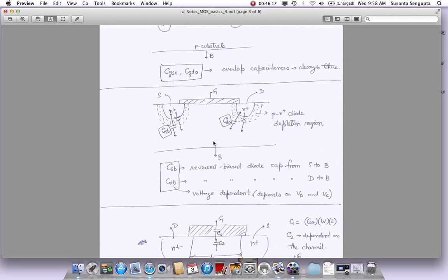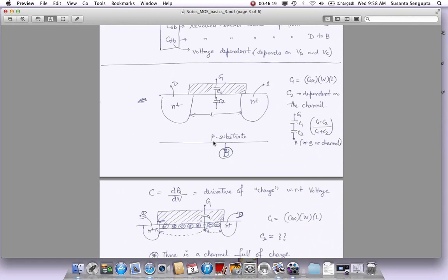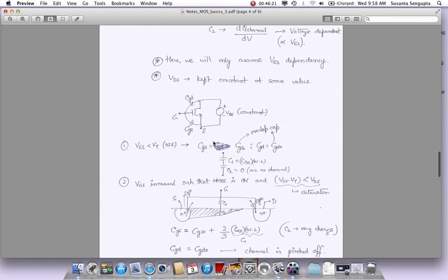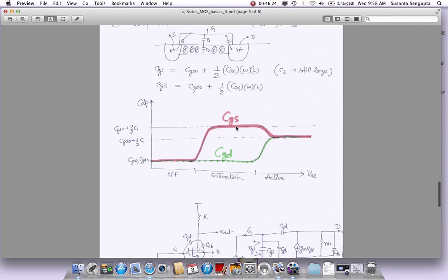These four you don't have to. What you really have to worry about, and what tends to become as we went through this section, is CGS. It always tends to be the biggest parasitic capacitor, and that causes the biggest frequency limitations that we see. How high of a frequency can you operate in? It is primarily determined by CGS. CGD also could become dominant based on how big these overlap capacitances are, but it is the CGS that you have to really worry about most of the time, and this is a plot that does that.